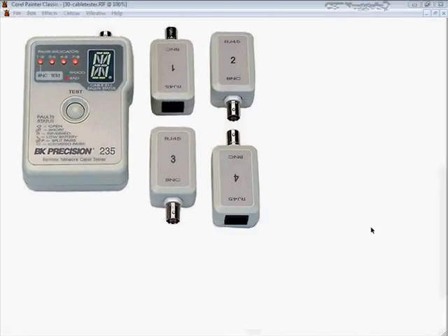Well, the first tool we have here is a cable tester, and these are electronic devices that we use to verify the electrical connections and electrical conditioning in a cable. And we've got testers and analyzers for twisted pair cables, of course, fiber optic cables. This is an older Ethernet cable tester. They usually have a combination of tools: testing the source of electric current, a voltmeter, and some way to test all the contact points in the cable.